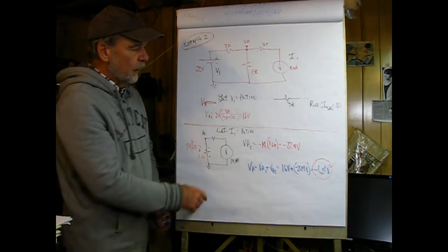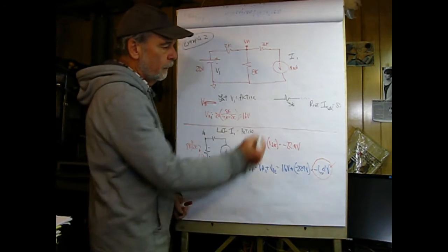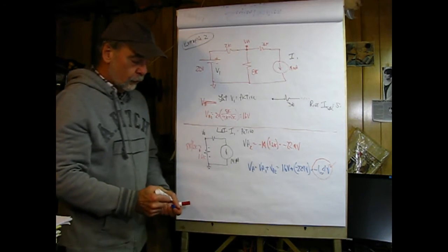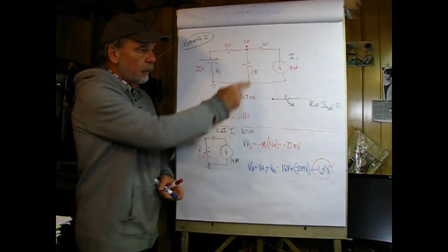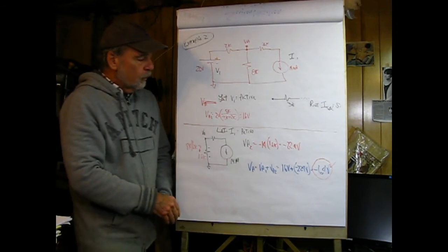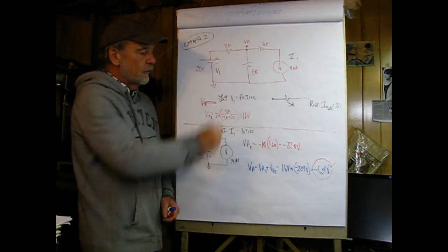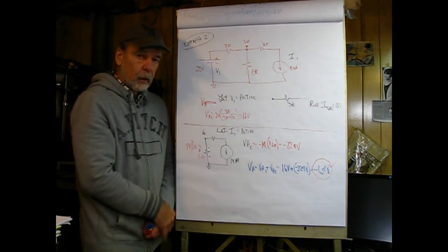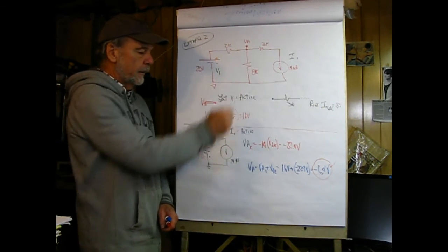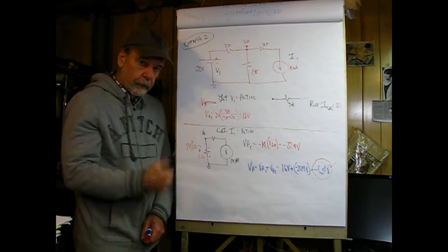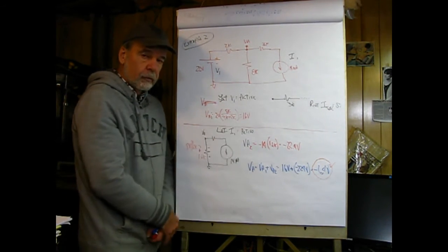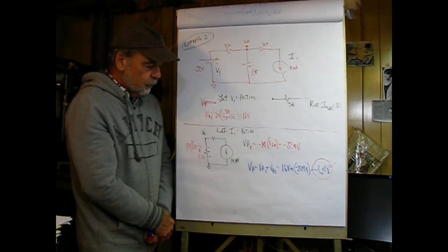What that looks like is I have the 3K resistor here connected to nothing. It's not in the circuit, hence there's nothing in parallel with the 8K. So that's pretty easy. We'll just find the partial response at VA here, calling that VA1, is going to be equal to our 20 volts times, in the numerator, 8K, and in the denominator the sum of the total resistance, and that equals 16 volts. So that's our first partial.